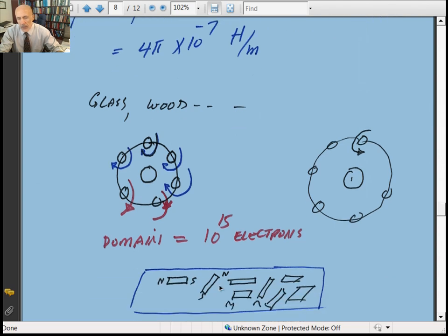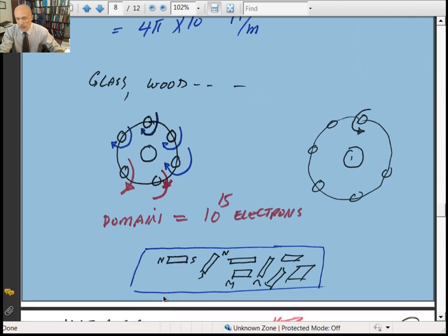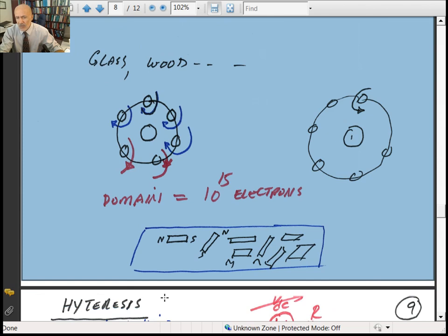Now, if you take a big piece of steel or any type of cast iron, and you look at those domains, they all scatter all over the place, and they cancel each other out. If the piece of steel gets hit by lightning, or you take another permanent magnet and slide it over, what it really does is line up those domains so that all of them point north-south in the same direction, so the magnetic field will add up. So that's really the source of a magnetic field.